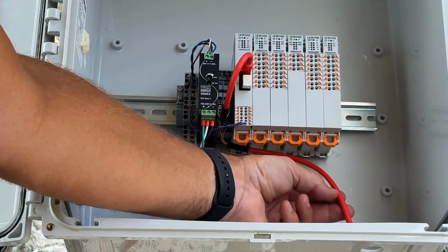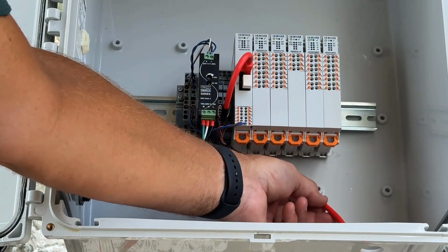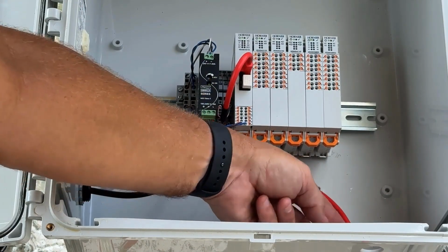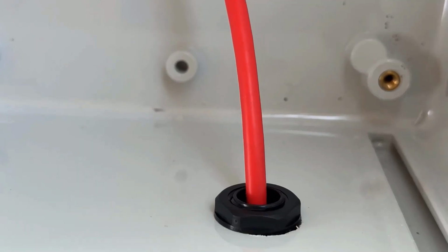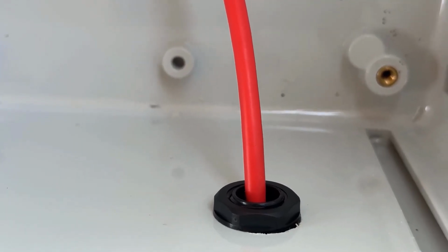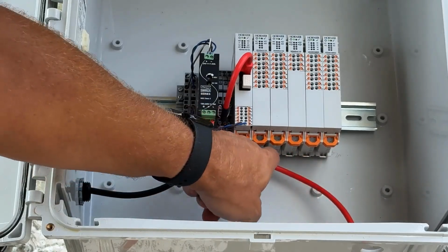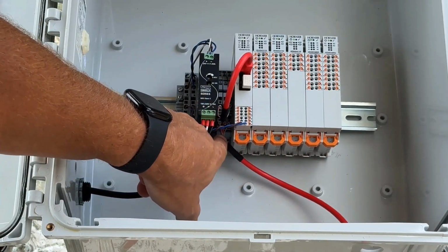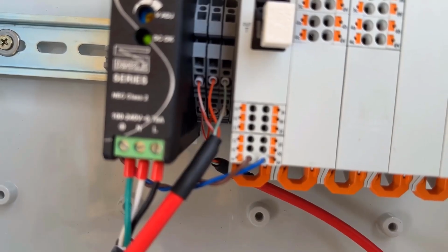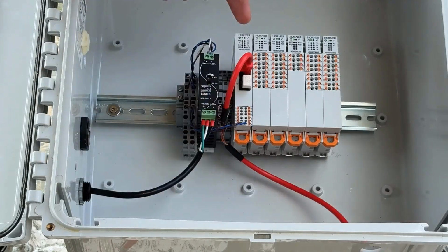In this scenario, we still have Cat5 or Cat5e coming in, but this time, instead of coming in through an RJ45 bulkhead, it is just coming straight through a traditional gland type connector for cable entry. And the 3 conductors for CAN are just being landed on this field terminal strip.